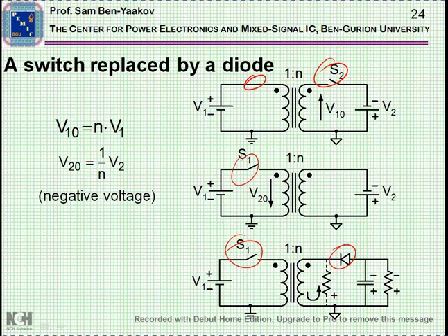What will happen is that when the switch S1 is turned on, the voltage imposed in here will cause a voltage of this polarity in here, and consequently the diode will be blocked because the polarity is reversed, and at this stage energy will be pumped into the magnetic core. Now once S1 is turned off, there's no current here. Now the current will start building up.